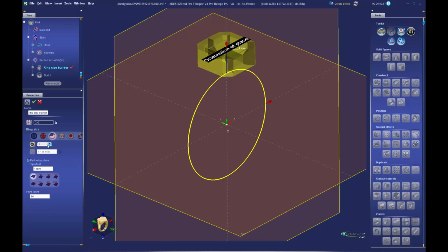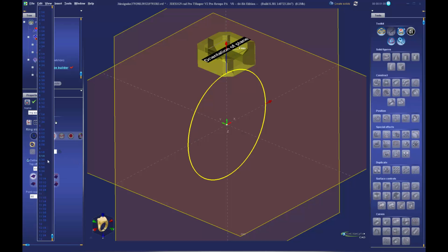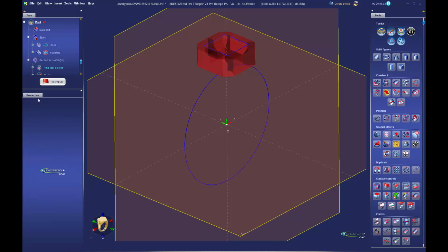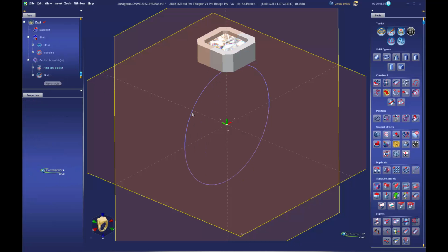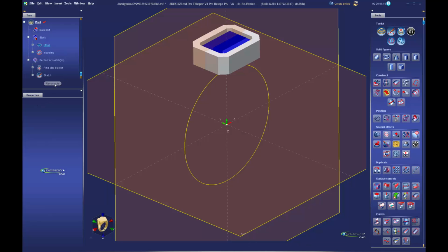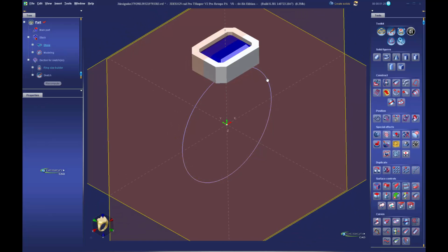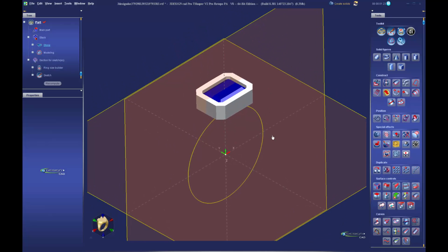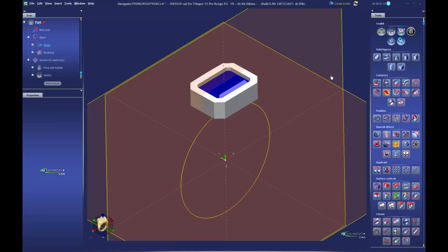So at this point, when you're going to actually create the final project with this bezel, you'll choose the finger size that you want to build to. Validate, recompute, see that our model is still parametric. We can also change our stone. So double click on the stone, and I'm going to do a 7x5 emerald instead of the default 5x5. Validate that, recompute, the sweep and the converted model updates. So like I said, at least we have this part saved as parametric. Next time I need one of these, I don't have to start completely from scratch. I can just go and modify the parametric symbol, and then we'll shape it from there.